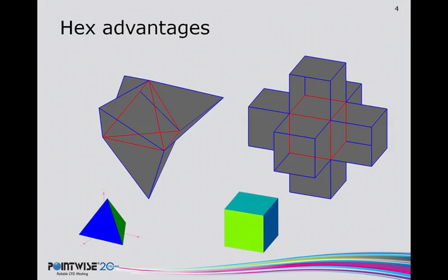Now, a quick little illustration here of what I'm talking about. On the left, you see a tetrahedral cell. This is just kind of an equilateral pyramid, you might say, with a triangular base. That's an important part. So every face is a triangle, and it has 4 neighbors associated with it. A hexahedral cell on the right has 6 neighbors, and in this perfectly orthogonal case, you can see that if the flow were perfectly aligned in this direction, all of the flux being computed whenever you compute the quantities being advected from one cell to another are going to be perfectly confined to this single face pair.